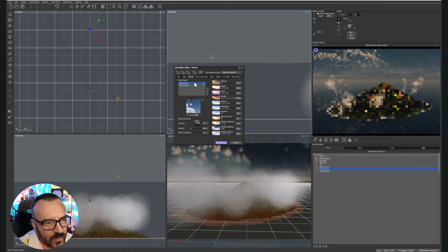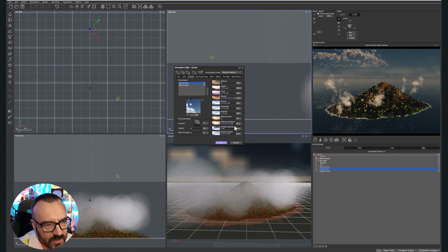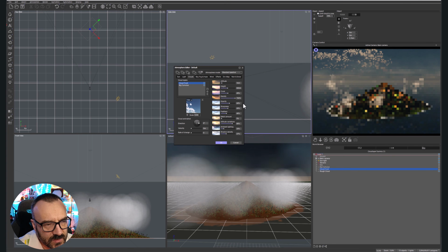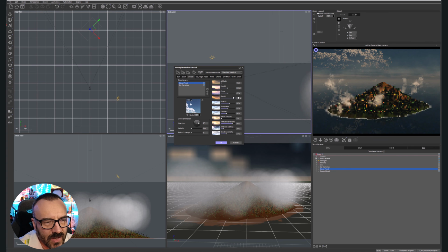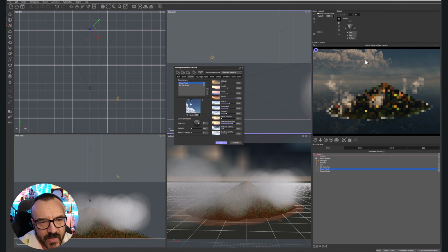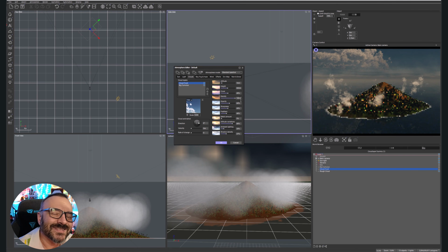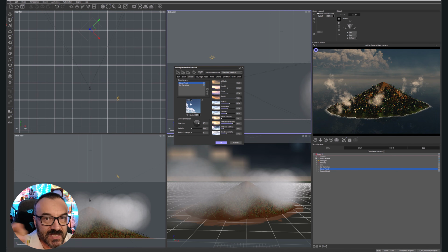We have cloud front. It's what we want to do. And we want to increase feathering, altitude variation, reduce shadow density. And look, this is the problem right here, density. 700 is kind of cool. You can reduce it a little bit to 100, which makes them a little bit less grainy. By the way, this is density in almost every field. You can type way higher numbers, but sliders allow you only to go to 100. So it's kind of a safe range, but you can modify.